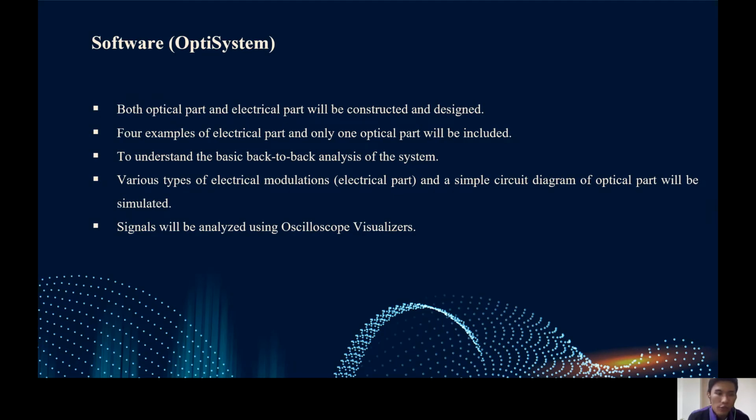In OptiSystem software, both optical part and electrical part will be constructed and designed. The main purpose is to simulate the optical circuit and electrical circuit and obtain the correct output at the receiver. And initially, 4 examples of electrical part will be constructed and only one optical part will be included in the OptiSystem software. The main reason is to understand the basic back-to-back analysis of the system. The input and output signal will be analyzed using oscilloscope visualizer.